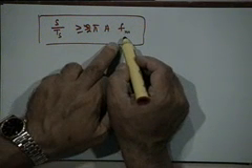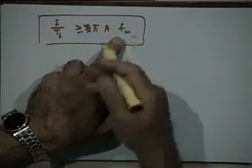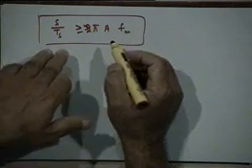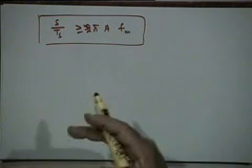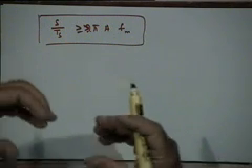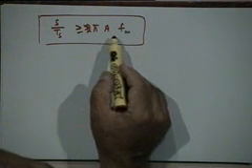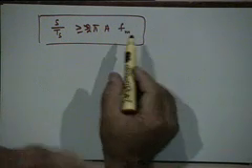So as you can see, for higher frequency messages the slope overload is more likely to happen than for low frequency messages. But fortunately, typical message signals have a very interesting property. For example, in the voice signal, the amplitude of higher frequencies is typically smaller than the amplitude of the low frequencies, and it is the amplitude and frequency together which dictate the slope overload condition. So it is the product of A into F_M which will be important.